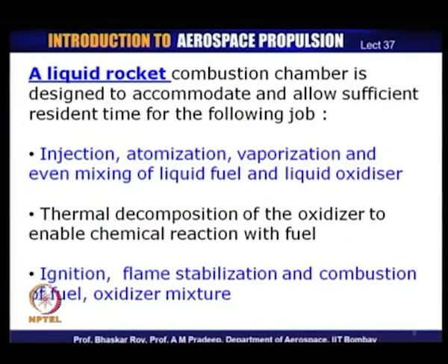Let us look at them one by one. The combustion chamber needs to have injectors for both fuel and oxidizer. So, you have two sets of injectors now, not one. One injecting the fuel, another injecting the oxidizer, and both of them have to do injection, atomization and vaporization, and then mixing of the liquid fuel and the liquid oxidizer in a correct proportion. So, this needs to be done.